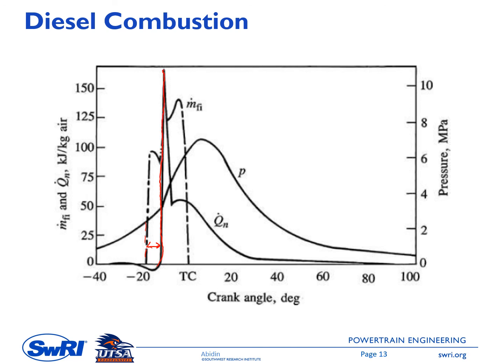You see there is a spike of the heat release rate, and as you will see later in the slides, this spike is because of the premix combustion. It is followed by a relatively low heat release rate, and this is called the mixing control combustion process.